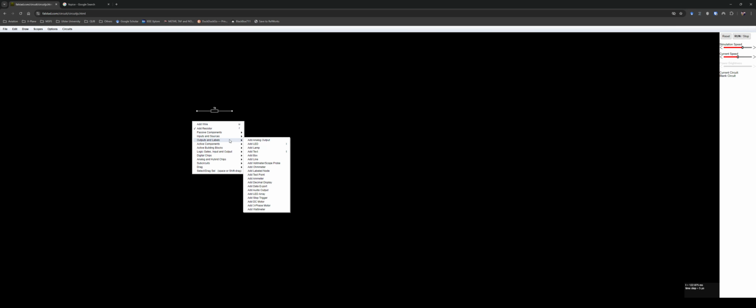When I am writing my own circuits, I usually do this. I'm not very good at drawing, and my inductor looks like a resistor, so I prefer to put it like this, to avoid mistakes. If I press Shift and left mouse click over it, I can drag. But if I don't press Shift, you'll see that I create another element here. To delete something I don't want, I just put my mouse on top, don't click anything, press delete, and it deletes. So for this first video, let's just do a basic voltage divider circuit.